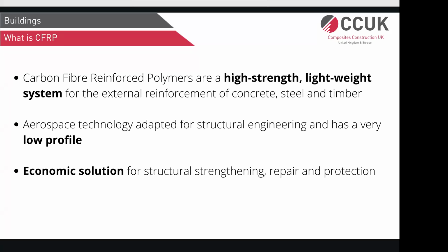Now, just to give you a feel in terms of numbers, carbon fiber is at least 3 to 4 times stronger than steel and at least 7 to 8 times lighter than steel. So you can see this strength to weight ratio, and why people prefer to use FRP over traditional methods these days is purely because the time in doing that strengthening is much, much less as compared to the traditional method.